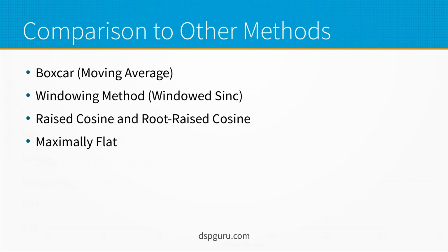And for most applications, you really don't need this kind of extreme maximal flatness. And if you think about Parks-McClellan design parameters, you can set that passband ripple to be arbitrarily low to whatever dB you want to, if you've got enough filter taps to support that. So a maximally flat type is maybe of interest for some specialized applications, but really it's not something you would use very often compared to a Parks-McClellan design with just a very small ripple in the passband.